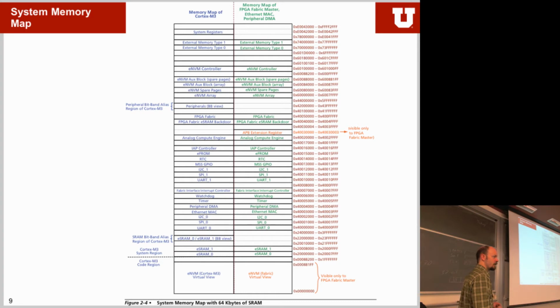Yes. So for example, they use the status as the storage register, and then for applying and changing things on that register, you use these 2 different registers to write into certain bits and to clear certain bits themselves. I think this is easier. This is also how it's often done, especially for things where you can get problems with writing and reading into it.